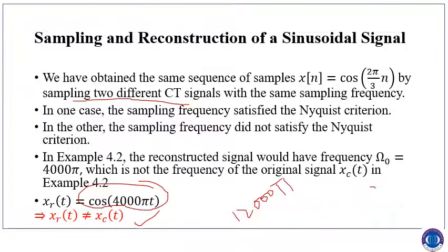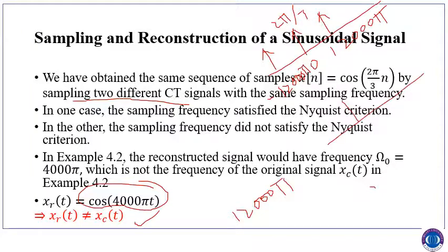x continuous of t. I can just draw an example here. These are the sampled impulses with area 2 pi by T. This is 0, this is 12,000 pi, and this is minus 12,000 pi, and then this is our signal, two impulses of area pi, one at 16,000 positive and one at 16,000 negative.